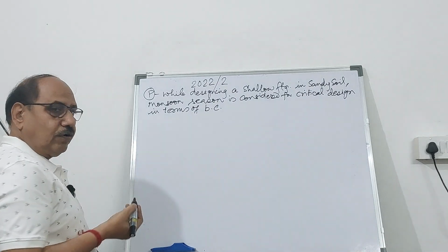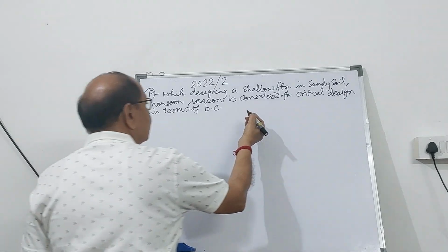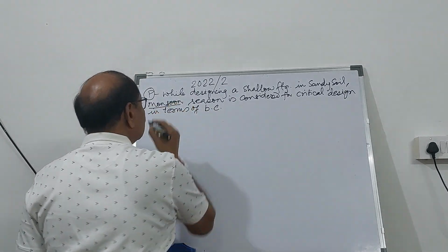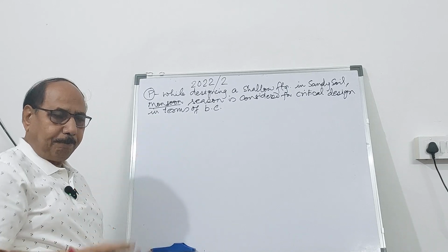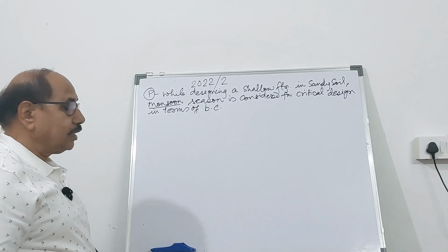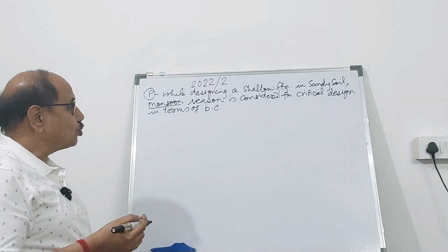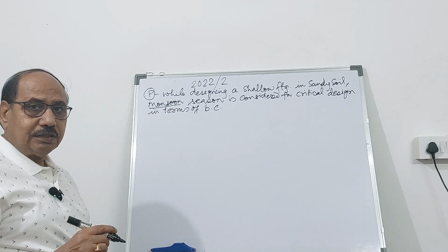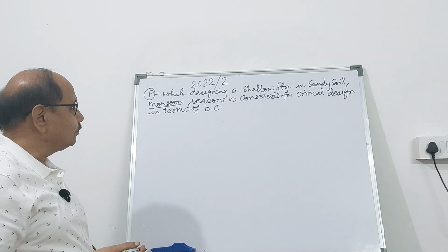Whether it is true or false, we can discuss it. You know that during monsoon, the water table is always going to come up, and sometimes it touches the ground level, and therefore the water table correction factor applies to both the second term of the bearing capacity equation and the third term.